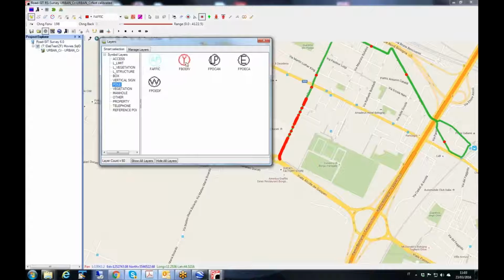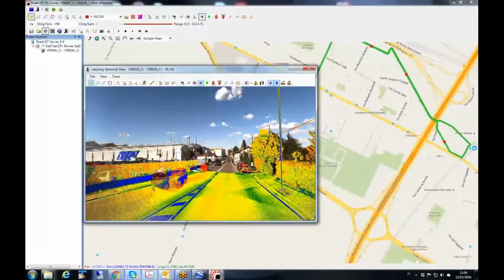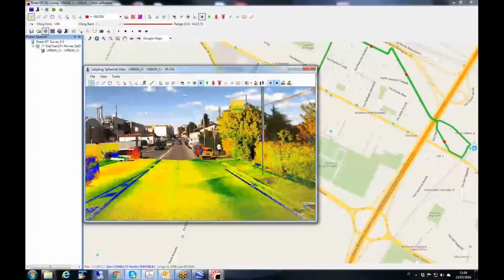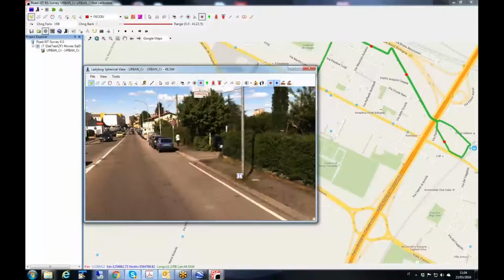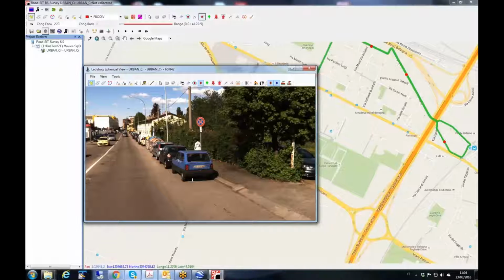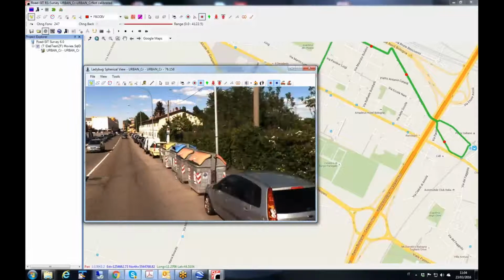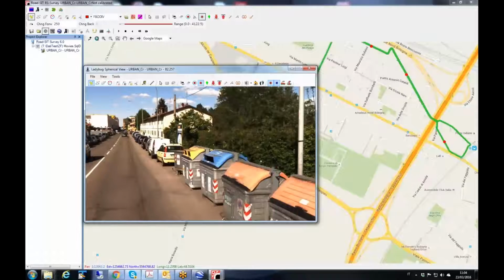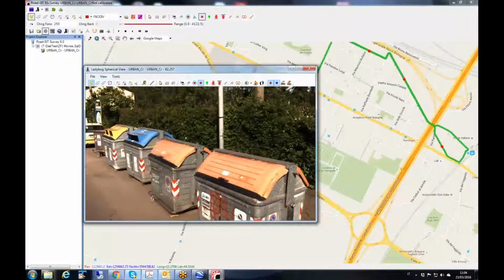Till now, I've shown you only the way to draw directly on the point cloud. But if you are not interested in precision, I mean, for GIS applications, and you can be satisfied with, for example, half a meter of precision, you can use directly the monoscopic positioning. You can see the vehicle plan.